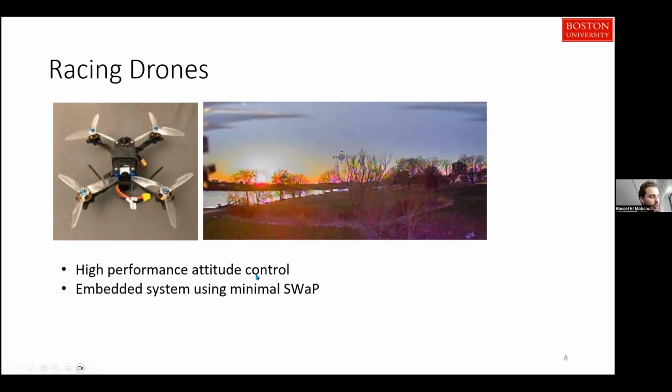What I mean by attitude control is allowing the drone to rotate about its central axis. So it's rotational control. You are trying to control the rotational velocity of the drone via some kind of analog stick. And that would be the person doing the racing. They're trying to get the drone to reach some certain angles so that they can avoid some obstacles. So it's still considered a low-level control task, and this is where PID control is used more often. And indeed, on any drone you'll find, it'll be a PID controller that's running on the stick.